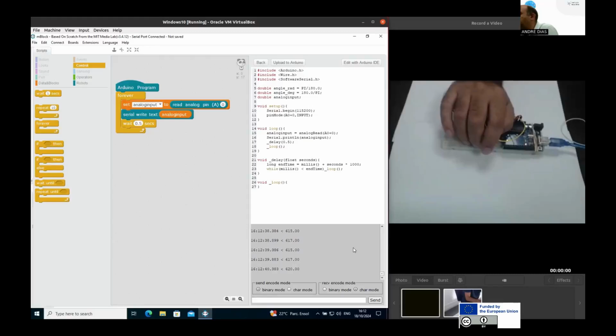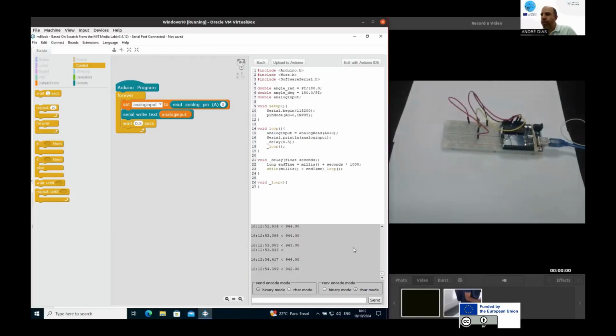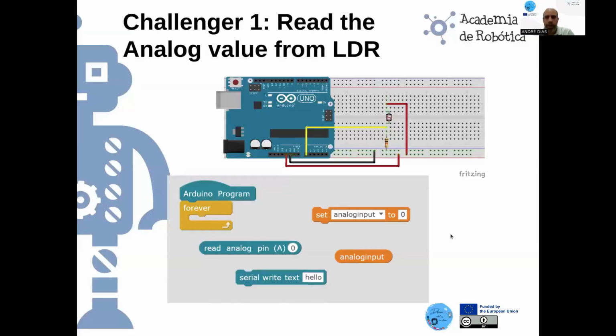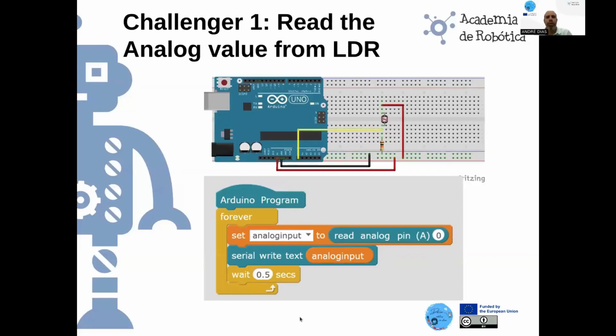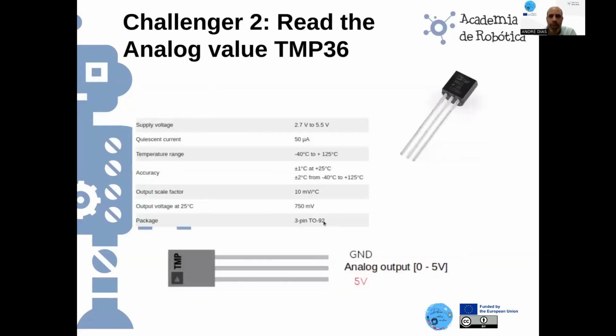Okay, if the light intensity is smaller, we can increase this value by having an external light that turns on when this value is smaller. Okay. Back again to the code. Okay. This was the instruction that we do. So we read the analog pin 0, store the information inside of this variable, and we show the result. Okay. This was one example of one analog sensor.